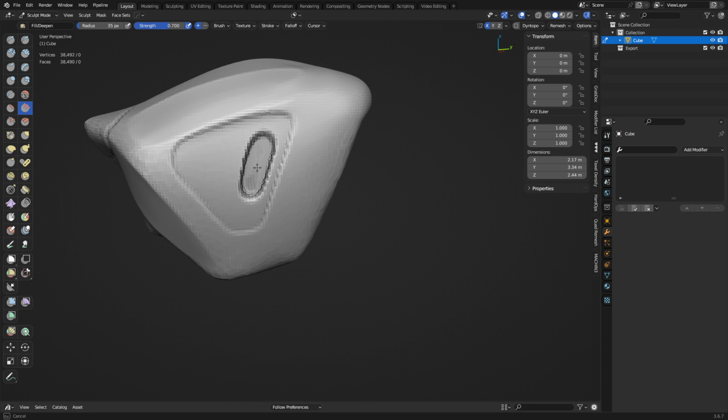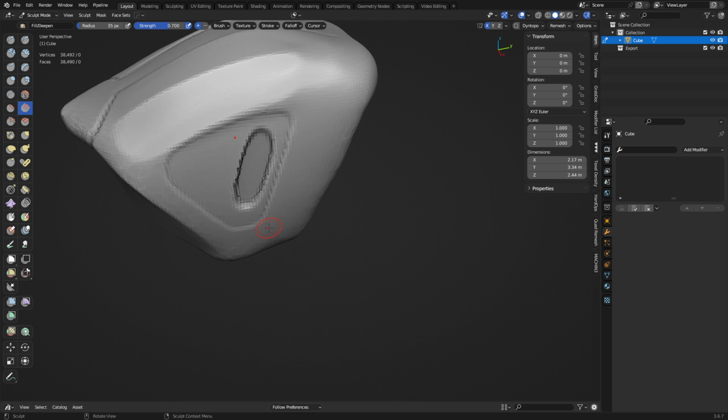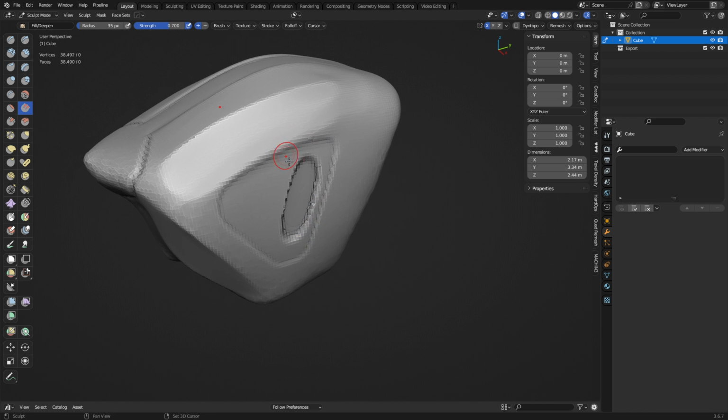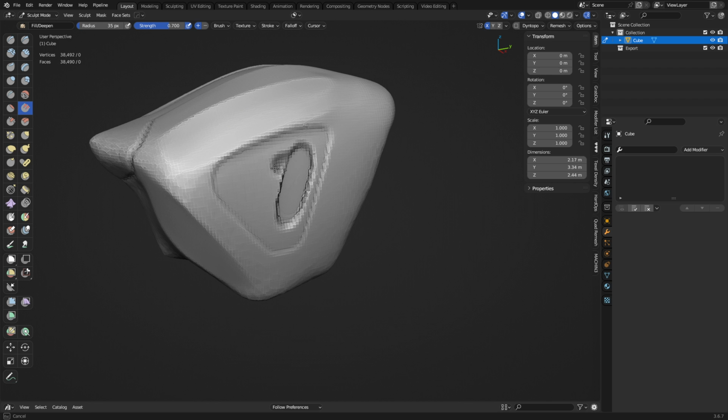But we're starting to dig into the surface there, almost like we're using the layer tool, which is nice. If we just let go of Control, we can fill that little area, and then hold Control again, and keep working, okay? So this is pretty cool, but it's kind of the same idea as the layer tool in essence, but you don't have to have that persistent base, okay? So you can go around and dig into a surface and just work it like such.